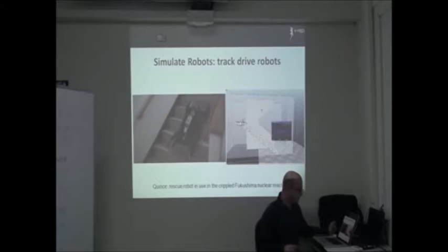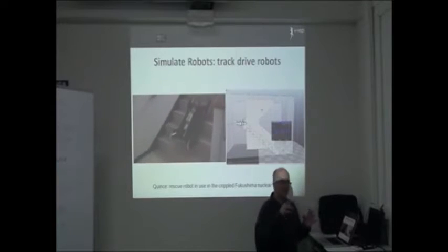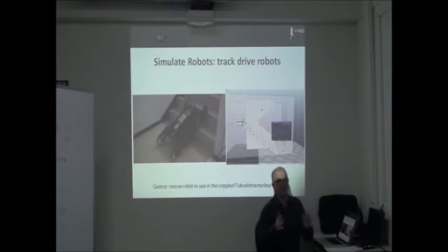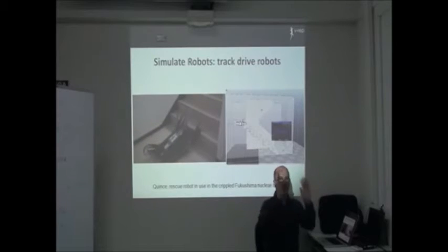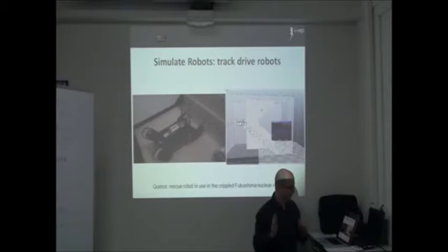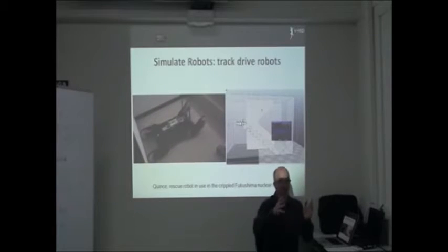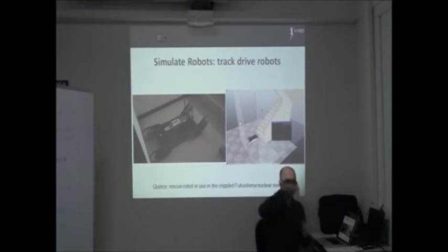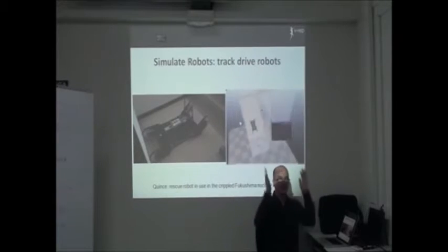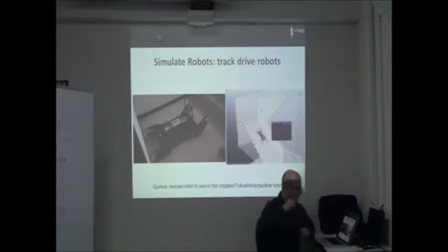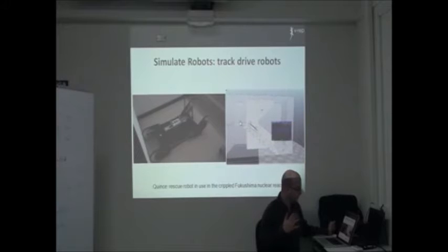So how does that work? I have one sensor that detects the distance and one sensor that gives me the pose of the robot, and some encoders to know where the flippers are. Based on how the robot is oriented, and depending on the distance it is detecting, whether it is the floor or a hole, I will update the flippers to maximize the friction for the mobility of the robot.